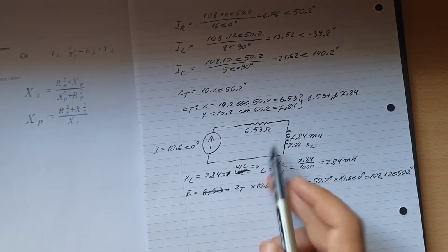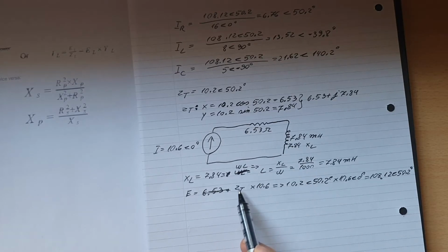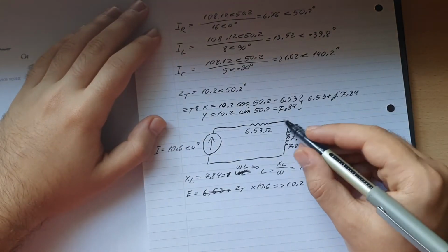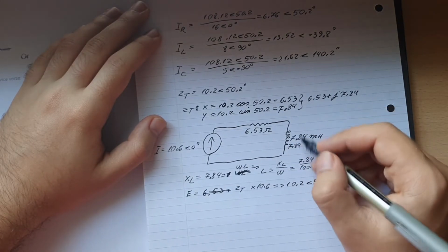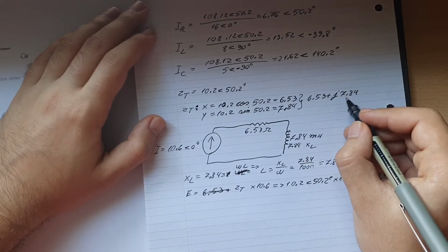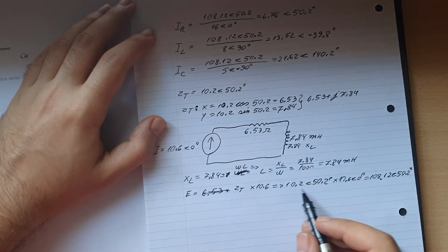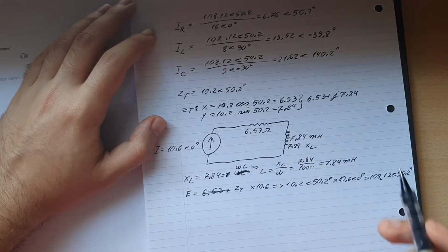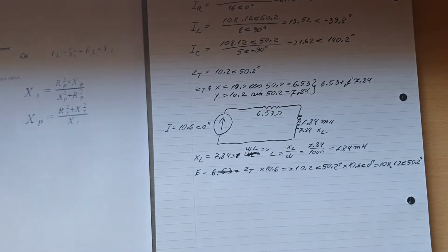And why is that? Well, it's because these two will still make the total ZT. And how does that work? Well, again, the resistor is a pure number, so the resistor is just 6.53, and the imaginary number, which will be the inductor in this case, will be a positive J of 7.84, and that's why ZT is the exact same number as the ZT that we calculated previously. All right,